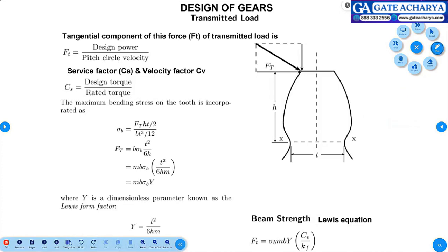So design of gears based on the load transmitted. While the transmitted load is concerned, we consider only FT. Normal part neglected. It is the tangential load which is going to create a failure at the root, not at the tip.